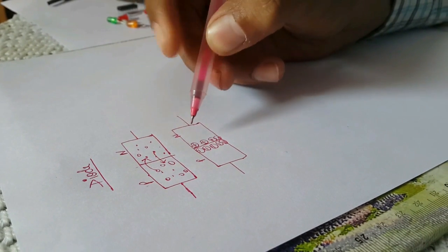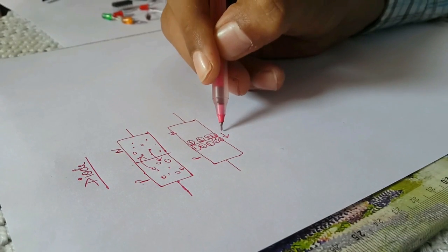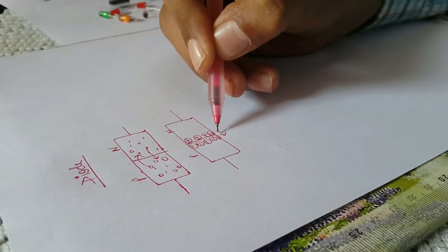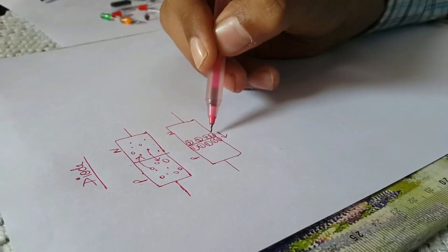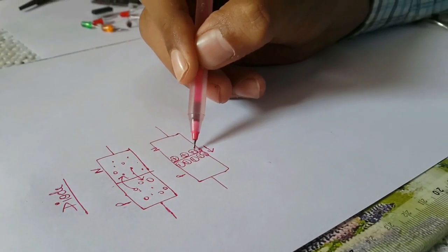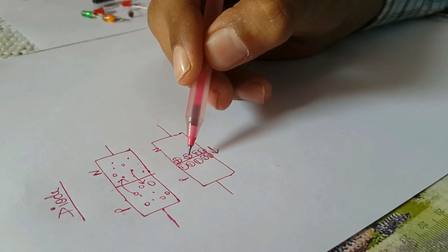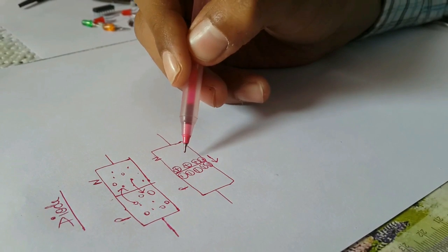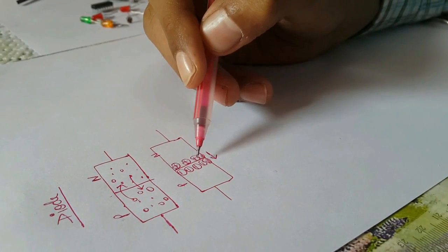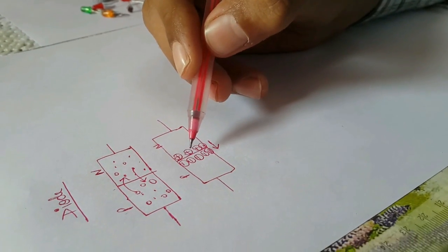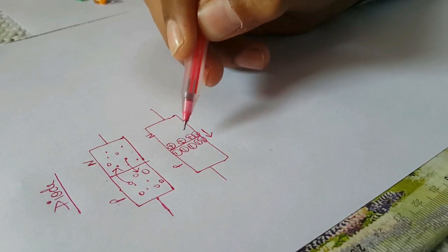Can you guess in which direction the electric field will be set up? It is from plus to minus, so it will be set up in this way. Now this electric field will create a potential difference across the junction, and that is known as the barrier potential or the potential barrier. This stops the further movement of particles from both sides. Holes we can't really call particles, since these are just imaginary vacancies, and they have less mobility than the electrons. Now what to do with this?